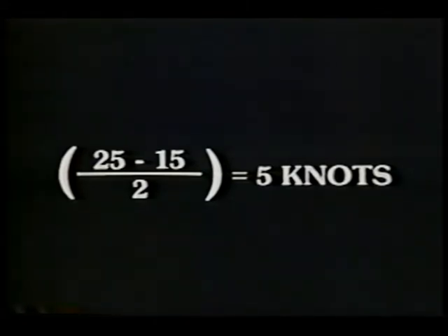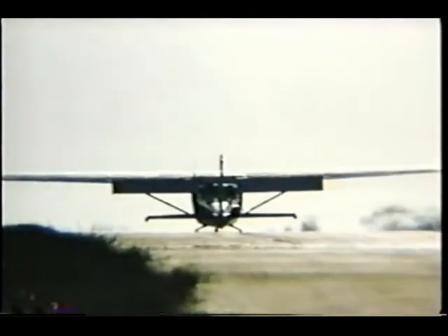Now, let's move on to a discussion about landing on inclined runways. If you've been flying for a while, you've probably experienced that strange sensation associated with landing up or down an incline. FAA Utility Airport Design Standards allow maximum grades of up to 2%, or about 1.2 degrees of slope. At such airports, runway slope is a comparatively minor factor.